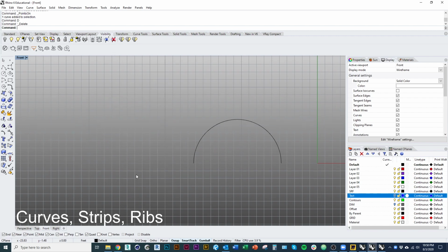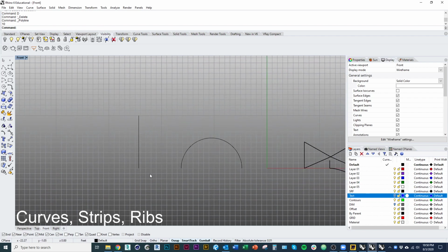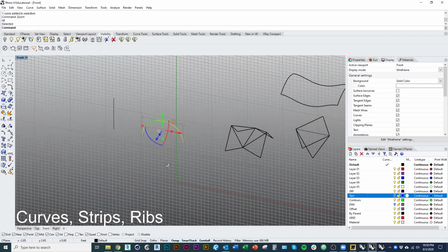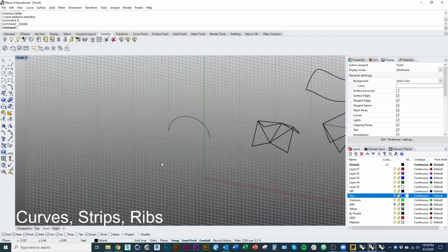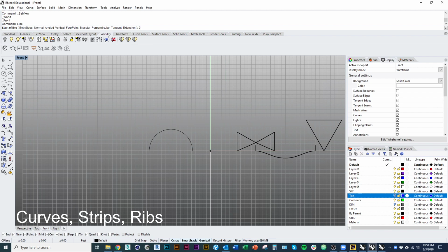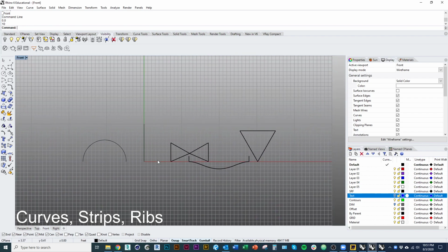Okay, so if I wanted to draw a symmetrical arch like this one using that command, what I might do is draw a construction line. So if I drew a vertical line at a dimension of 10, and actually I should be careful here because I'm not drawing on my plane. I'm kind of behind the plane, so let me restart that. If I draw a vertical line, I'm just going to start at 0,0, and I can do that by, instead of clicking in my viewport, typing a coordinate in the command line. So 0,0 is going to be at the origin of our file, right? That's our XY coordinate. Then I can type in a length for that curve and press enter. Now I'm holding shift to keep the line straight vertical.